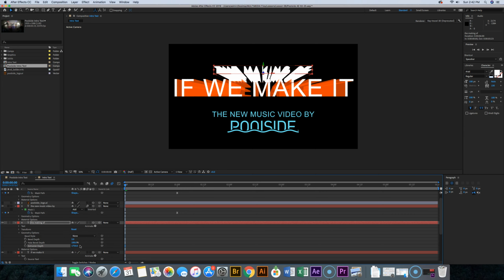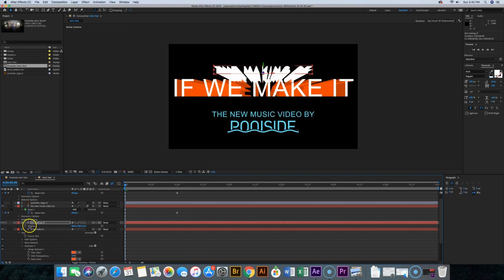Now what we're going to do is move this whole layer, this Making Of, forward in Z space so that the backs of both of them are lined up. To get that to happen, we need to press the P key to bring about positioning of that layer. And you notice we now have 3 different options. We have the X, the Y, and now we have a Z axis that's currently at 0. So instead of having it be there, we're going to move it forward 250 pixels. And now it comes out from that point.